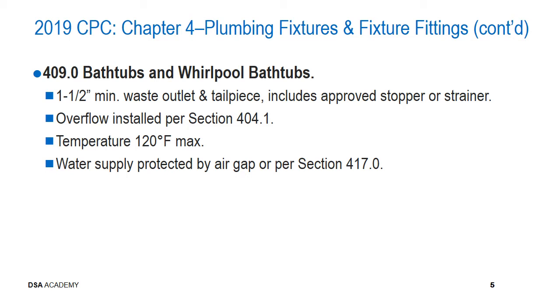The water supply has also got to be protected by an air gap or per Section 417, and obviously that's because we don't want cross-contamination. Nothing has really changed, nothing new there, but it is important because of its uniqueness.